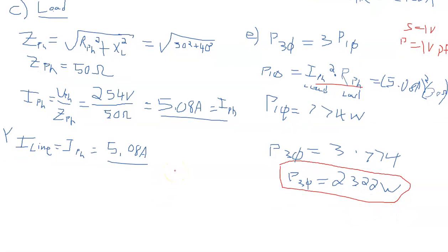Because we said earlier that the equation that we should be using to calculate P three-phase is root 3 times V line times I line times the power factor. And that requires a bit more work from us than our 3 times I squared R, because we got root 3, and remember now we're generally doing this for the load.